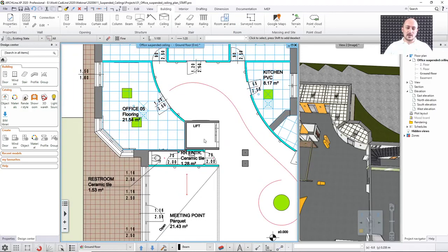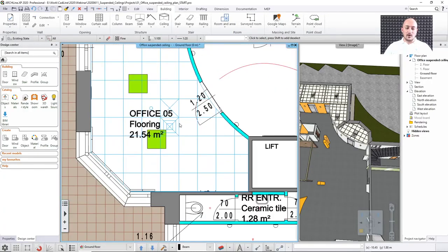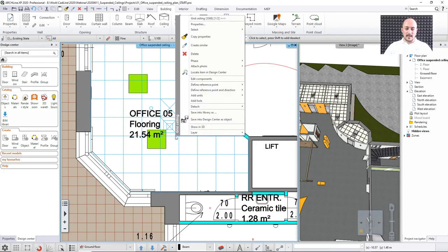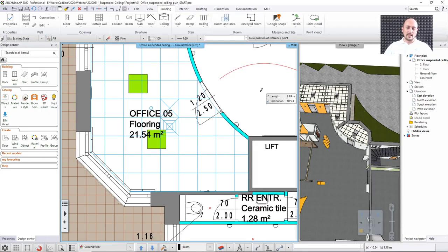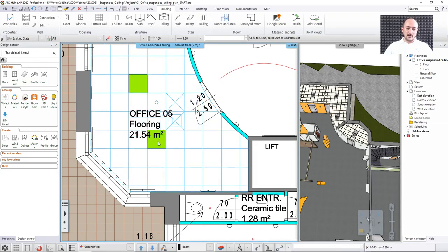Okay, so now let's just come here, and here I will now only fix the position, and later I will tell you how to add additional individual units and how to realign or replace them if they are not at the proper location. But now let's just focus on the first issue that we need to fix, and that's the alignment of the grid. So I click here again with the right mouse button, and then I say I would like to define the reference point again with the unit corner, and then it's automatically aligned. So it's 2 clicks and you're good to go.